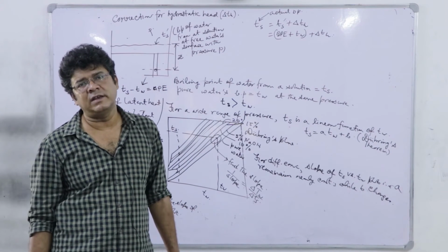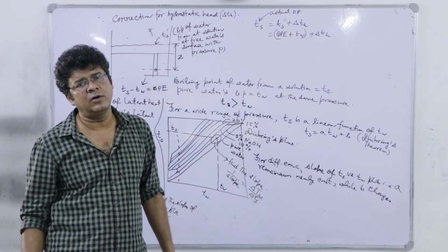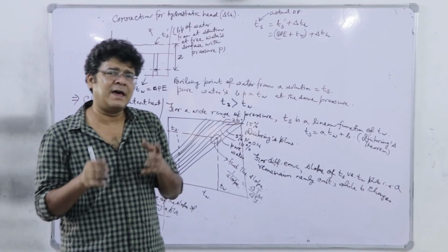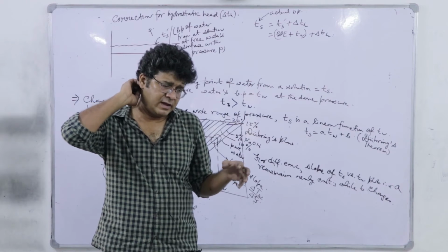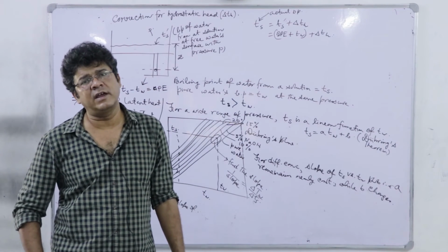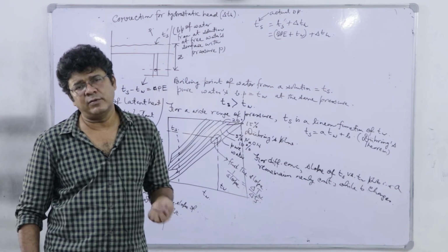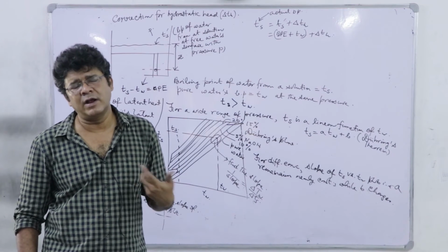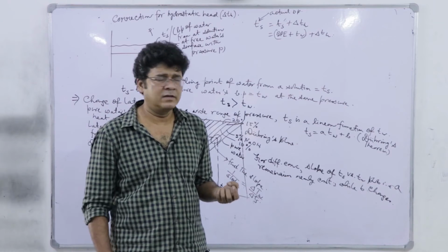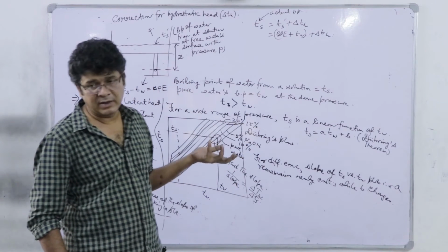At the critical point the latent heat of vaporization is 0, at the triple point it is maximum. So Clausius-Clapeyron is valid close to the triple point, right, but as we move along the vaporization line towards the critical point, the validity is questioned, and it gives more and more inaccurate results for the boiling point elevation.